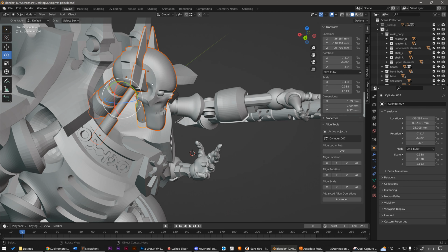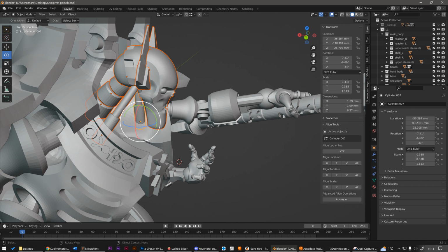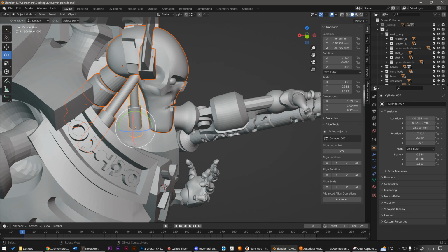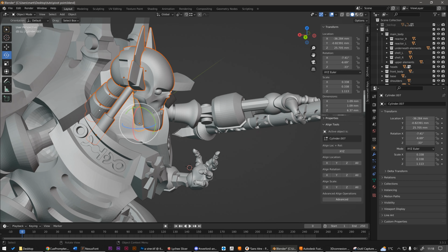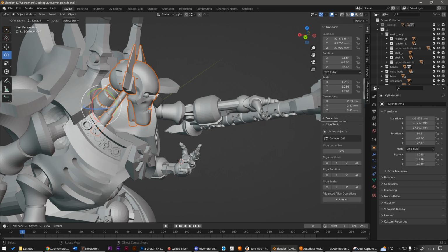To do that, we can tell Blender to place the pivot point on the active element origin. Let's try that right away by going back to the Pivot Points menu with the semicolon shortcut, and there we choose the Active Element mode. So the active element, as a reminder, is the last object we selected with the Shift key, and it's outlined with a light orange. So there the piston is the active element, so the pivot point is positioned on its origin, but since we want to use the vertebra's origin as the pivot point, I reselect the vertebra again, so that it becomes the active element.